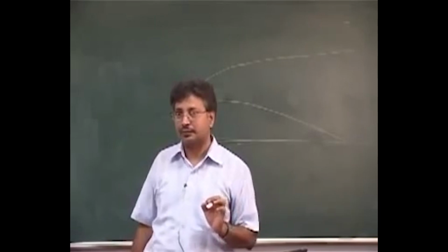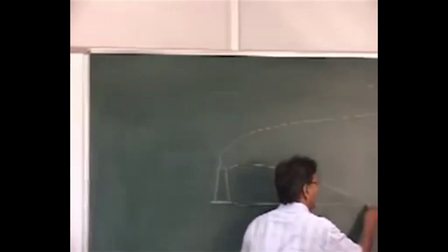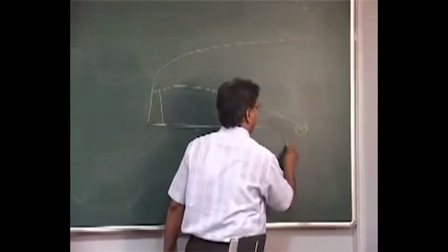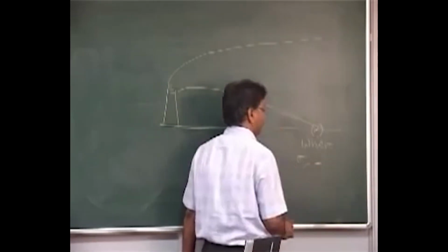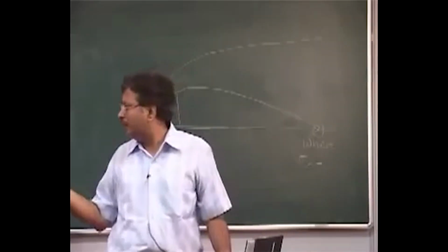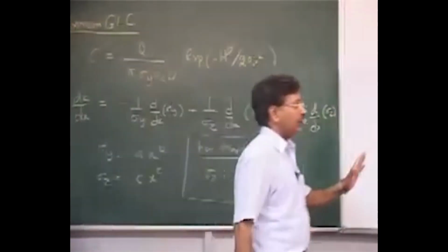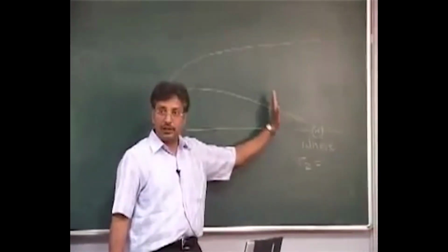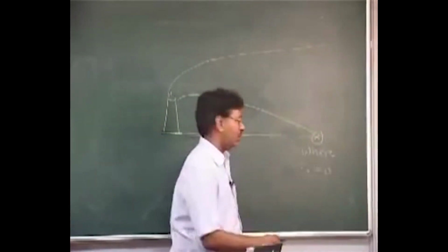Maximum impact of an elevated source. So I am just telling you that this situation may be somewhere here where sigma Z has become equal to 1 by square root 2. That is 1 by 1.41, which is 0.7 something. So you see here that sigma Z, which is constantly increasing with respect to X, is nearly equal to 0.7 of H, so I will write that number.